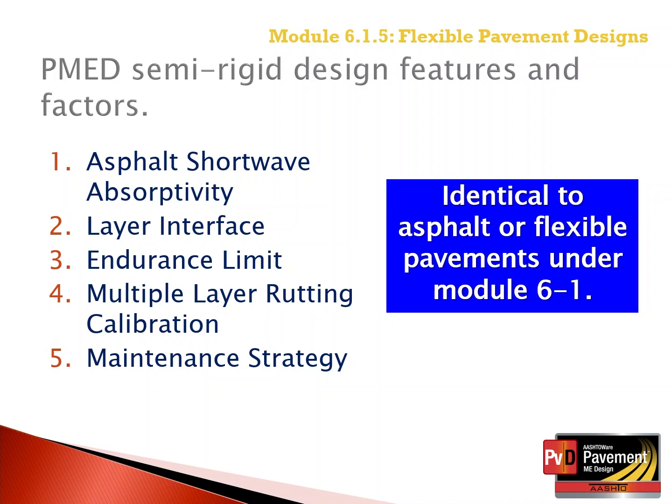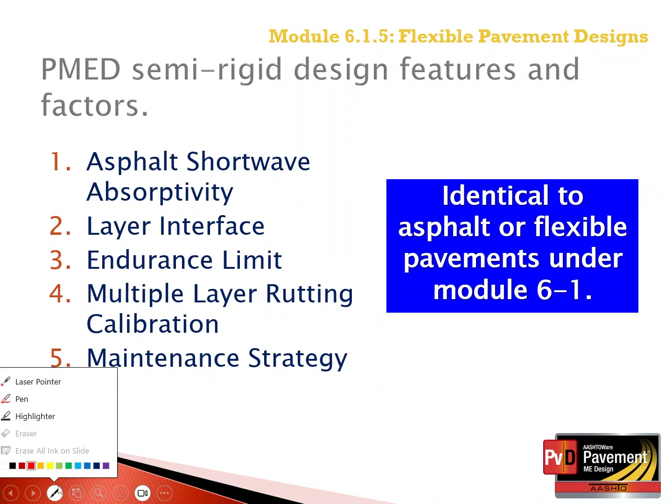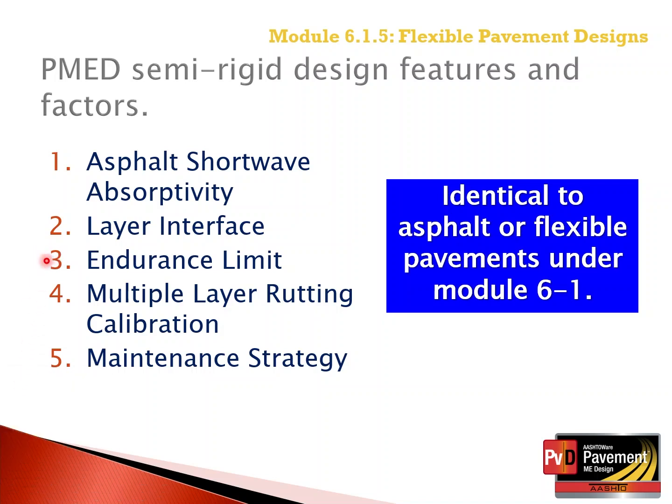So these are the five features or factors as they relate to semi-rigid pavements: asphalt short-wave absorptivity, layer interface, the endurance limit, multiple layer rutting calibration, and the maintenance strategy.